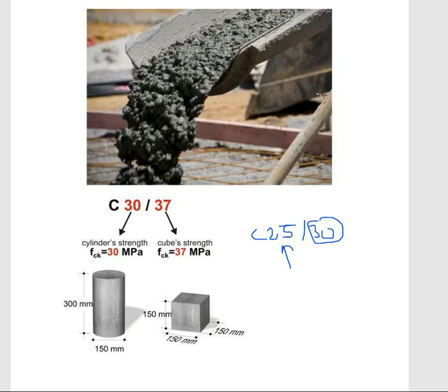For bigger buildings with columns or heavy loads, engineers may use stronger concrete like C30. But strength classes are not chosen only by the load. It also depends on the exposure, like rain, seawater, chemicals, and the environment. More aggressive conditions may need higher quality concrete.